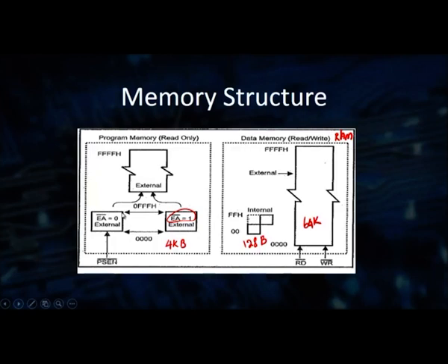If you are getting from the internal, then the external access signal will be high. If the signal is high, it represents that you are accessing the data from the internal. When the signal is low, you can get the external memory with a maximum of 64 kilobytes. So, based on your design requirement, you can get any kind of memory. That read operation is selected by using the PSEN bar. When the signal is active, that is when the signal is low, you can get the data.